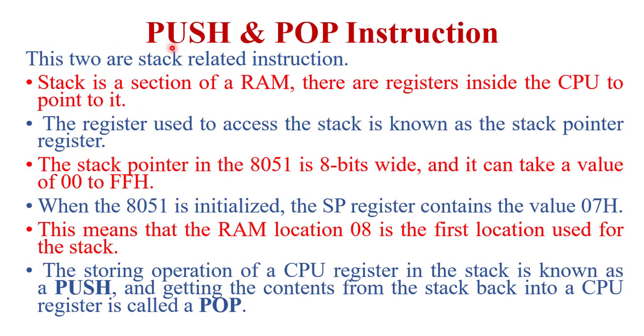Next data transfer instructions are PUSH and POP instructions. These two instructions are stack related instructions. So first we should know what we mean by stack. Stack is basically a memory location, or we can say that stack is a block of memory in 8051 RAM which is used to store data temporarily. Whenever the microcontroller is dealing with an interrupt, to store the content of the program counter and PSW flag register, we use the stack area of memory. So in short, we can say that stack is a part of memory in the 8051 microcontroller.